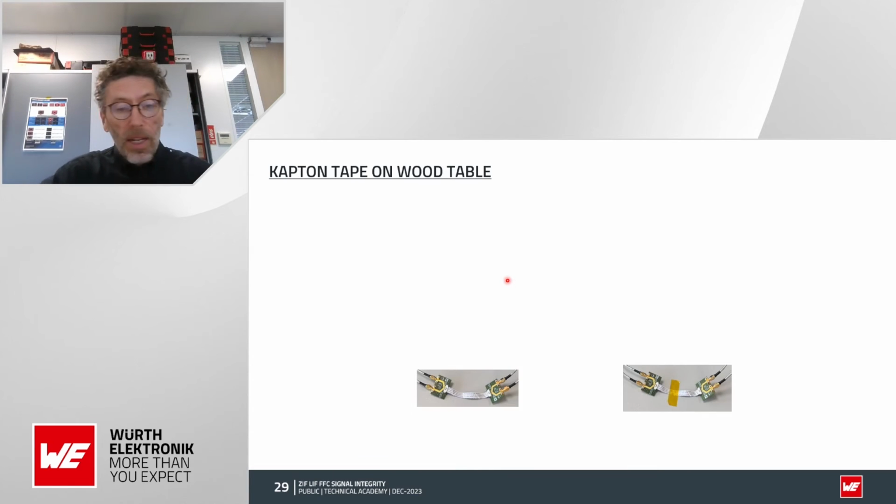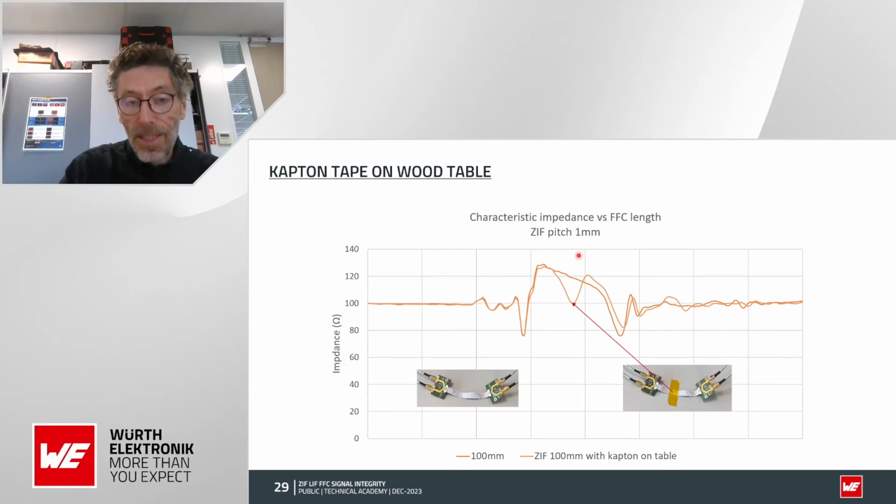You have vibrations on your system, and you don't want the FFC to be moving up and down all the time, then you take Kapton, this is a Kapton tape here, any kind of tape, and you stick it, that I did on the table. This is a plastic wood table. Does it have an influence on the signal integrity? Yes, you see that the impedance changes.